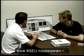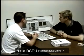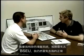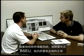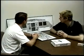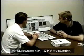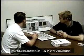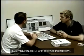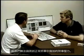What about the scenario of losing both channels of the BSCU, but we still have green hydraulic system? If I've got green hydraulics, but I lose the BSCUs, I still lose my normal brakes, and I lose anti-skid capability. Since you can't detect brake pressure, we've lost anti-skid, but we can't detect brake pressure being applied in normal brakes.